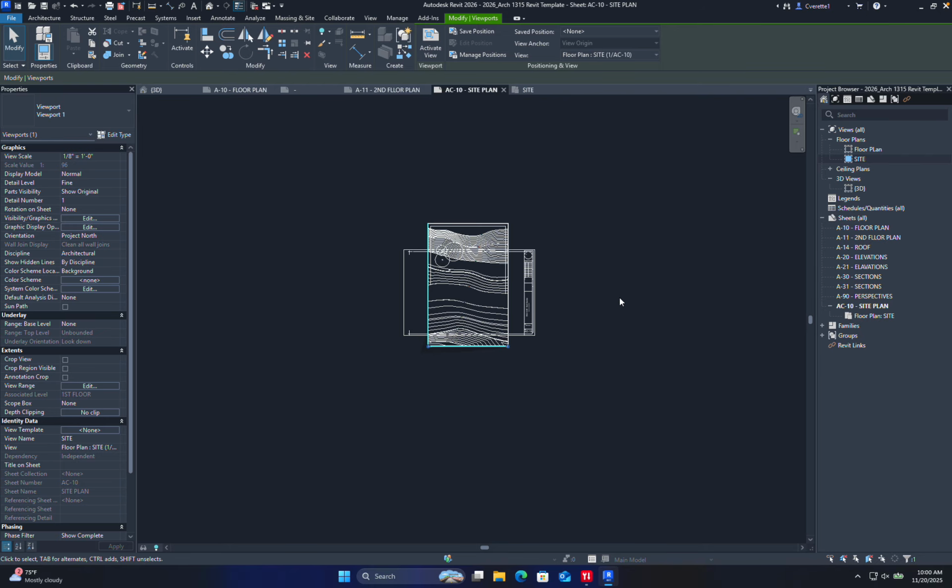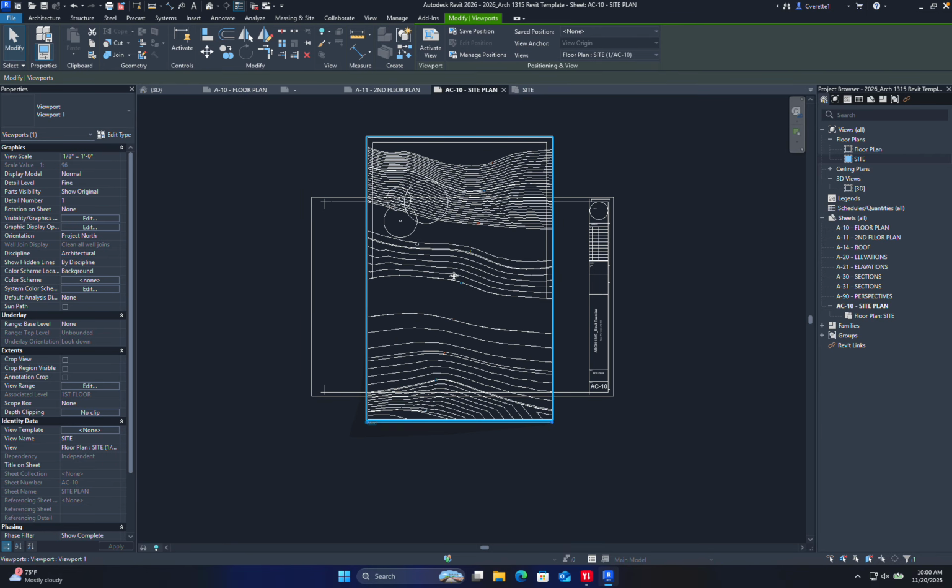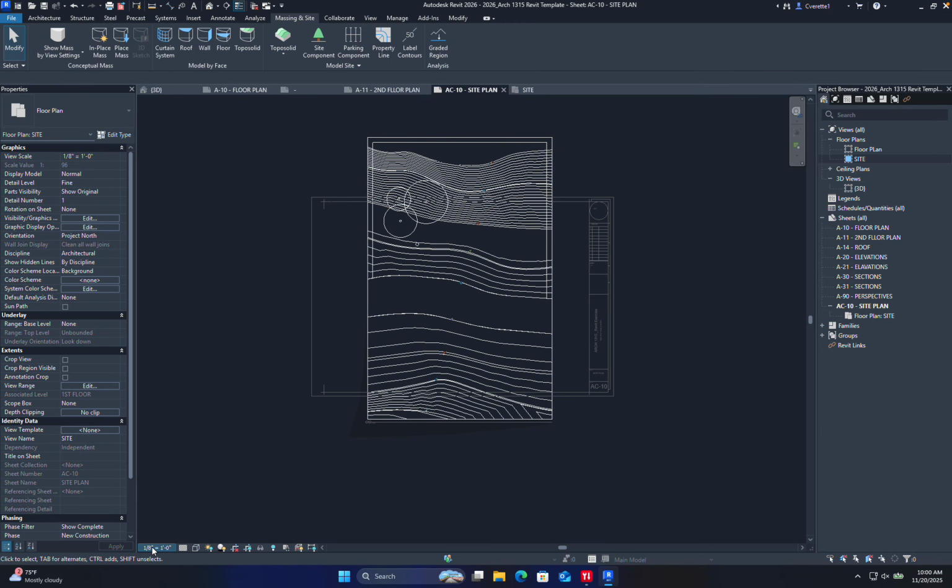This is the part that I think students love the most: yes, you can double click on the viewport, and you'll see that you can change the scale on the click of a button. So right now it's at 1/8 scale on a 24 by 36 paper. Again, so many things are already done for us, and for good reason. We don't want to pay $55 an hour for somebody to be making a title block over and over again. Wild that we even used to in the 90s with AutoCAD, and we did, and I was there.